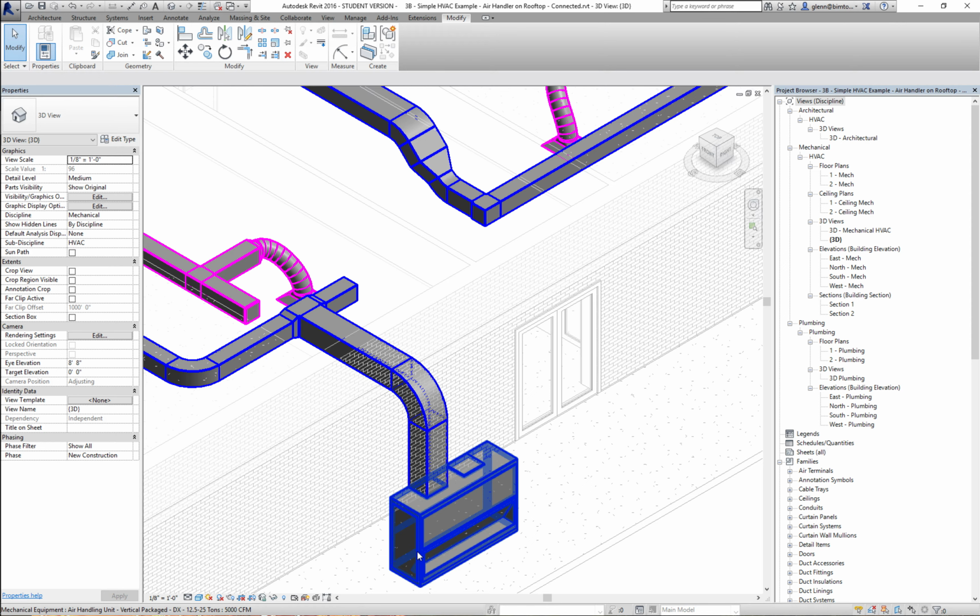So it's always good to put things at a fairly local location, but it's quite common in many buildings. For example, if you have a 2 or 3 story building and you're thinking about a single air handler up on the roof, you can have it feed a vertical duct, and then have that connect down to the different levels. Let's demonstrate that sort of strategy.